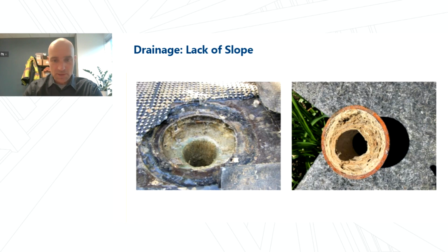These are a couple lessons learned from plazas that had inadequate drainage. What happened here is that water ponded or stagnated on top of the membrane. And as the minerals that the water picked up mixed with air, they formed hard deposits that could either clog the drainage mat, the drain body, or the drain pipe. For a while, the owners were able to keep up with pressure washing the drains and the drain pipes. But eventually the deposits became too strong and built up too quickly. They blocked the flow of water out of the drainage mat and in the drain pipes.